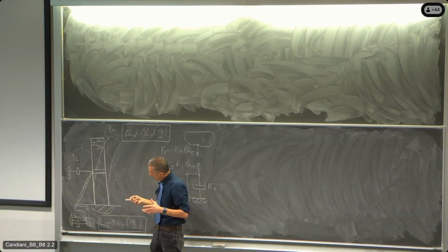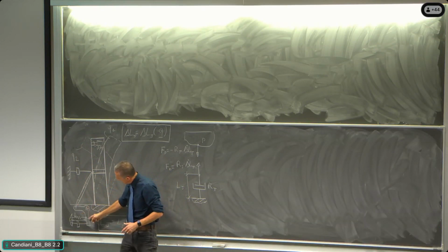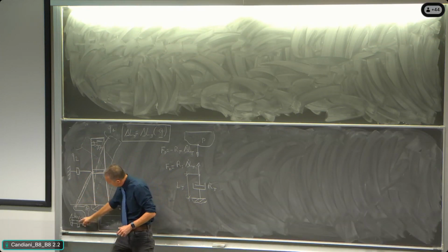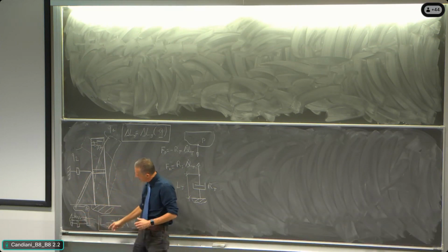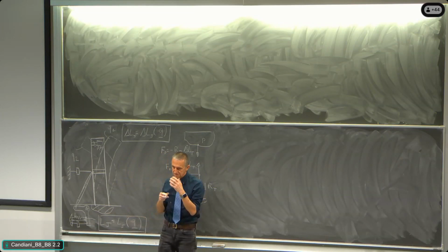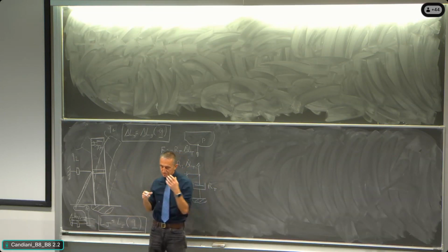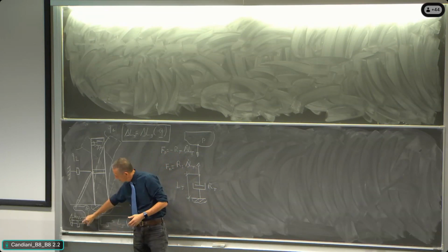Okay. So there is a connection here, then there is a device, and this device is bringing the movement to a damper. But then there is also a spring. There is a spring because you can understand that the movement can be a small movement, and so if there is a clearance among the different connections, you could have a small movement that is not transmitted into the damper itself.